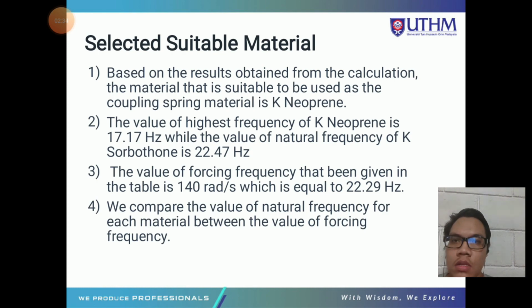natural frequency is close to the forcing frequency, it will cause trouble and problems to the system. So that's why we choose neoprene as our material that is suitable to be used.